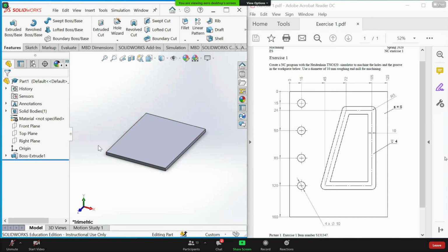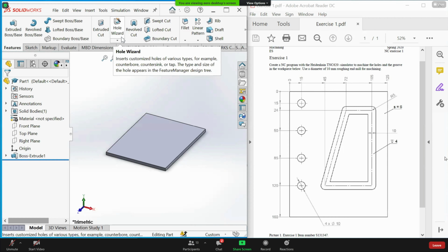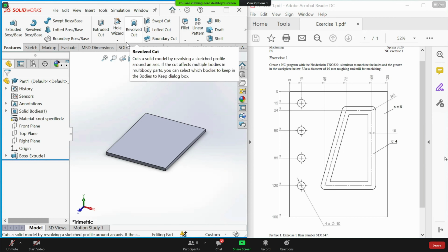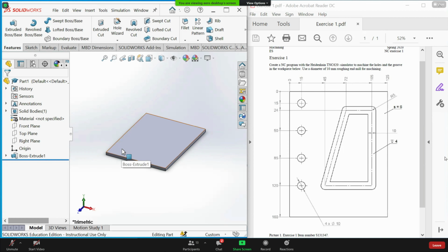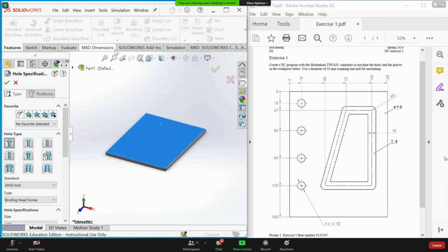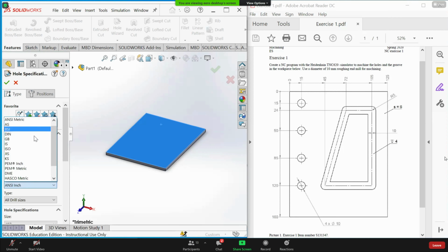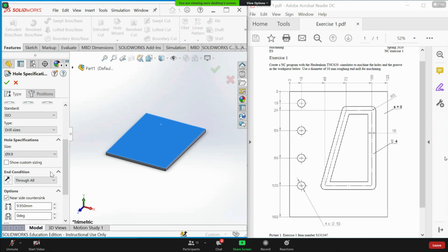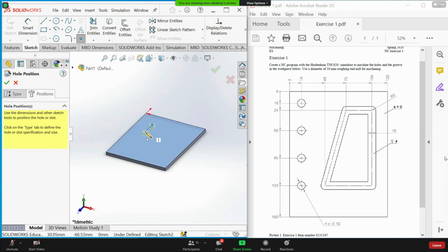It's best if you plan to use SolidWorks CAM and your part has holes in it, like shown here. There are 4 10mm holes. It is best practice then to use Hole Wizard, because it has a benefit that all the holes made by the Hole Wizard are recognized as drilled holes in SolidWorks CAM, which means that it can automatically select the corresponding work cycle for the drilling operation. So let's add the holes, 4 times 10 millimeters. One, 2, 3, and 4.